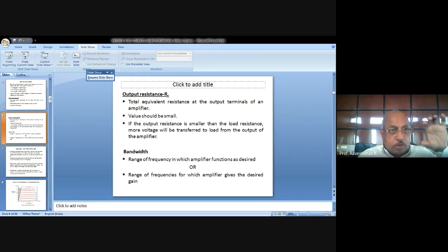When Vin varies, the input signal IB varies. During the positive half cycle, the positive signal voltage will be added to the DC voltage. So IB increases during the positive half cycle and then decreases to 0, and coming to the negative half cycle it reduces, isn't it? And for a CE configuration, we know that the current gain beta is equal to IC by IB.